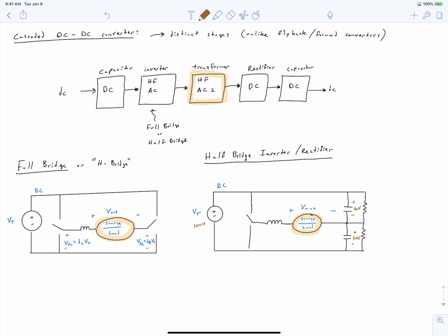And so similar to how in this converter on the left side, the full bridge converter, we're able to control the left and right duty ratios independently in order to get left and right pole voltages that are independent. So for example, if we have a duty ratio on the left side equal to 75%, then we're going to get a pole voltage of 75 volts. And if on the right side our duty ratio is 25%, we get a pole voltage of 25 volts, which would give us a total output voltage of 50 volts.